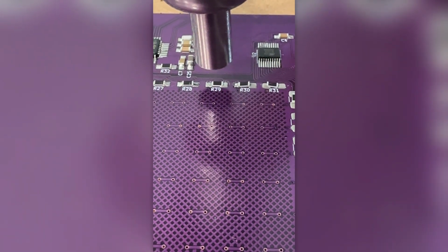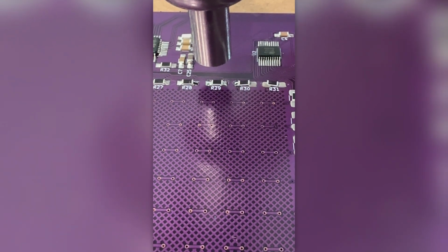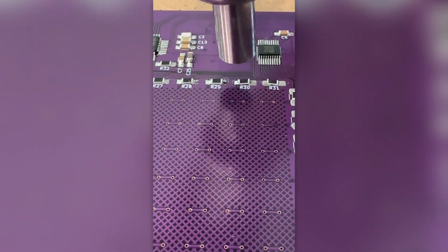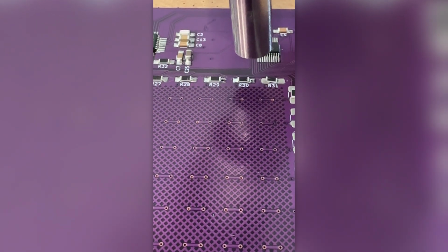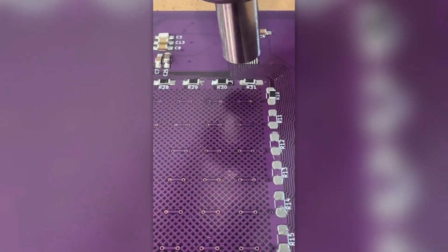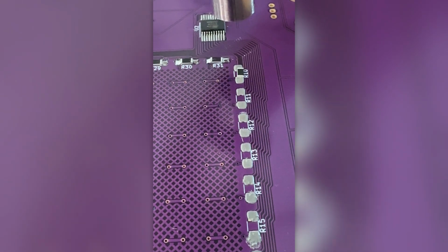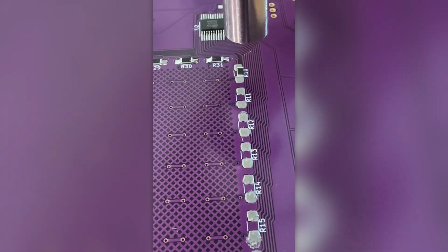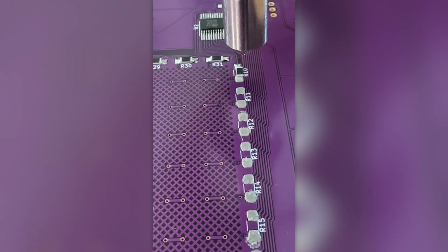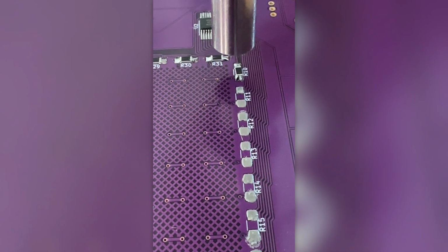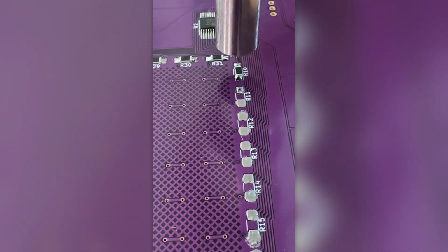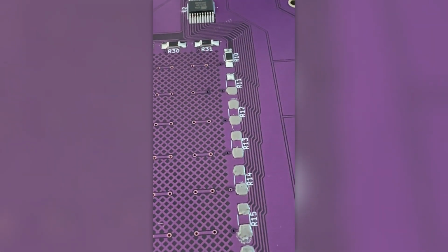So there I am, soldering it down, using a hot air gun. It's pretty cool how the solder itself kind of sucks the component directly to the board in the position it needs to be, assuming it doesn't blow it off first. There were a hell of a lot of these. I shorted out a ton of connections and had to get a soldering sucker, suck it off, try again, especially on those little microprocessors with the fingers you can see in the background. But eventually the day did come where I got most of these on.